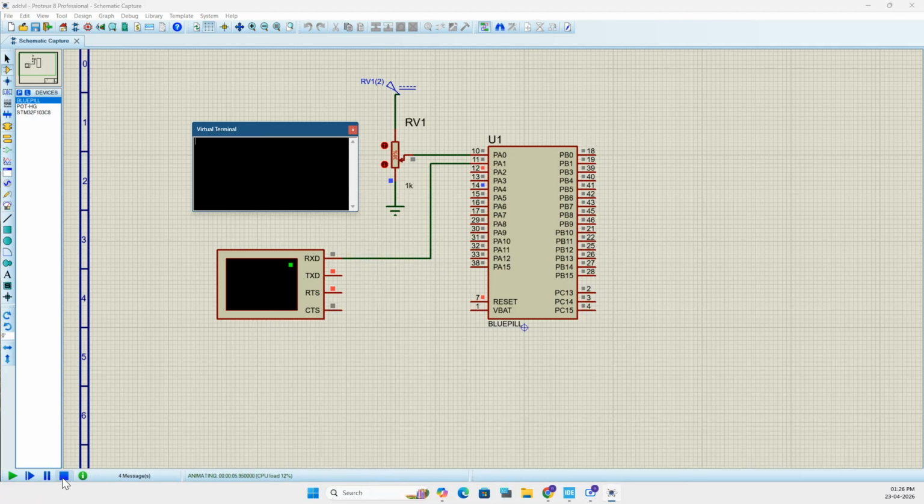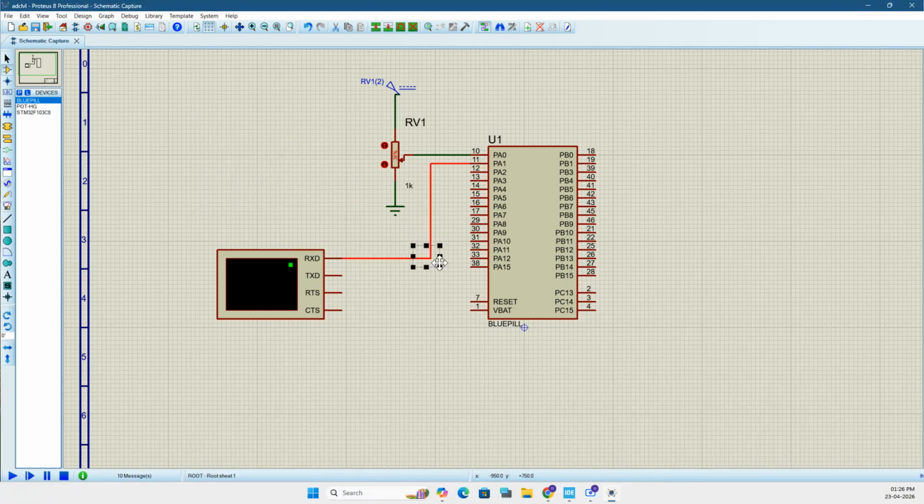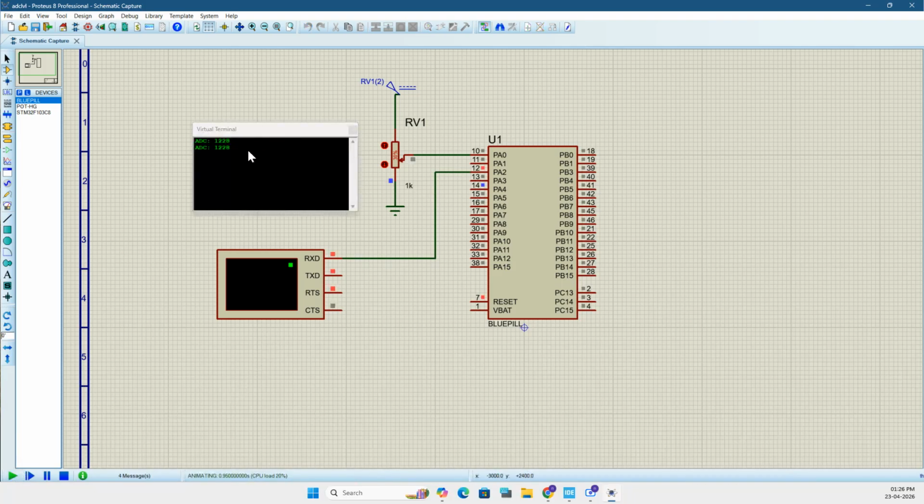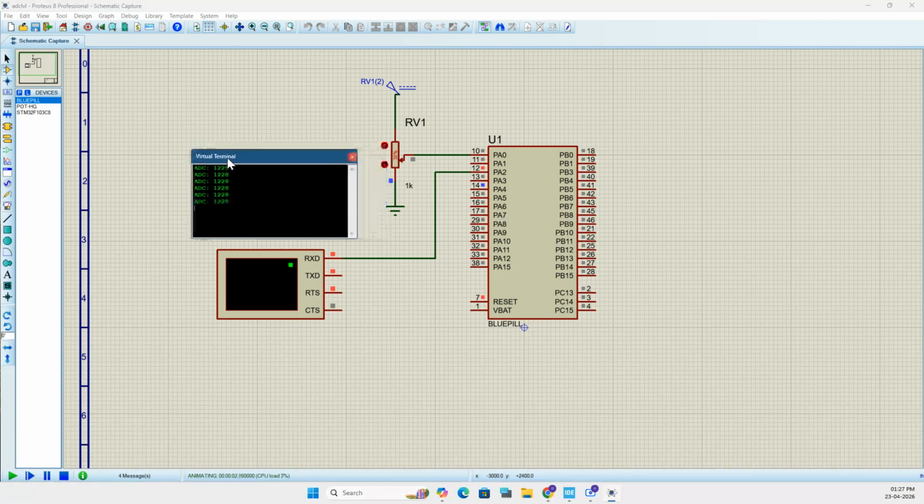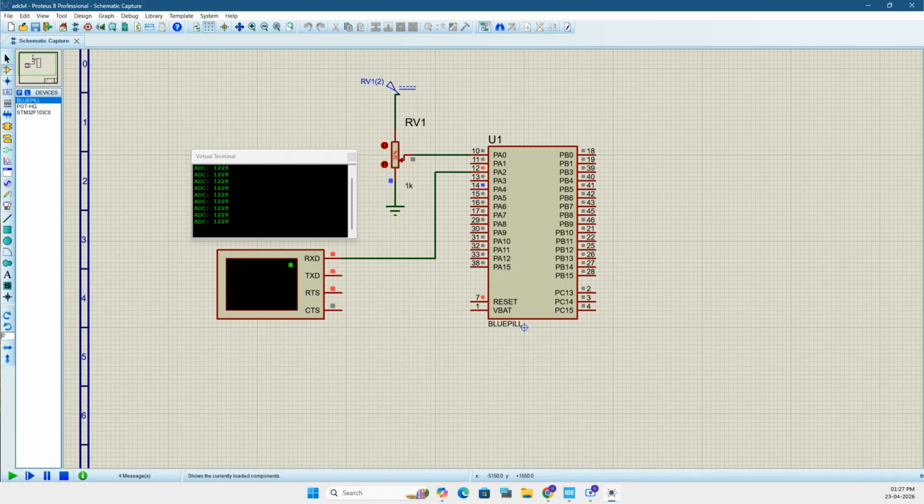Okay, it is not showing anything. There is one slight wiring mistake. So this should be PA2. Let's run this. Okay, now you are getting the proper levels for ADC. That is what we want. Now if you watch the documentation of Proteus, you are not going to find the answer why that problem exists. But if you are proficient in Proteus, you can watch the register banks and figure out that the previous controller we were using was broken.